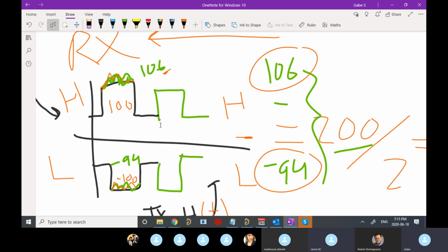Or the stop and start bit, is that something you predefine to say it's going to be low? Or is that just the standard? I think that's the standard. Correct me if I'm wrong, Mahmood. Is there an active high start and stop bit? No, I think that's just part of UART communication. Yeah, I think usually the line floats high and then they pull it low to start.